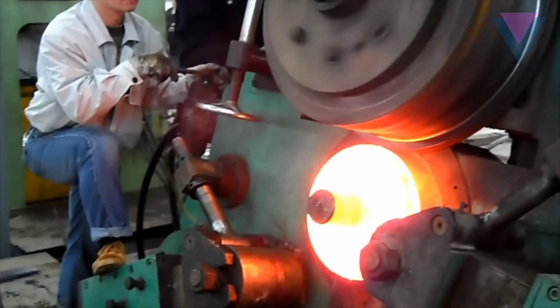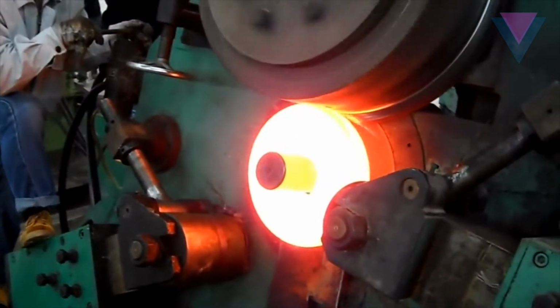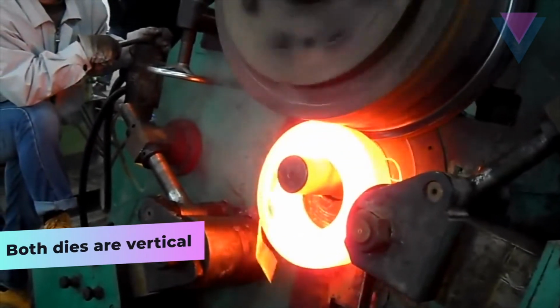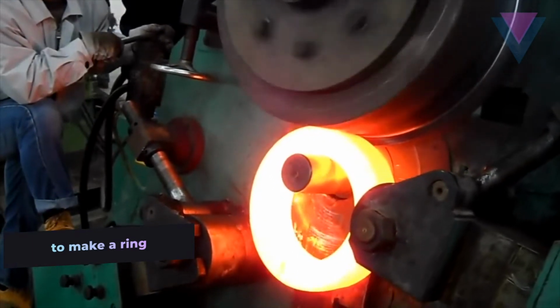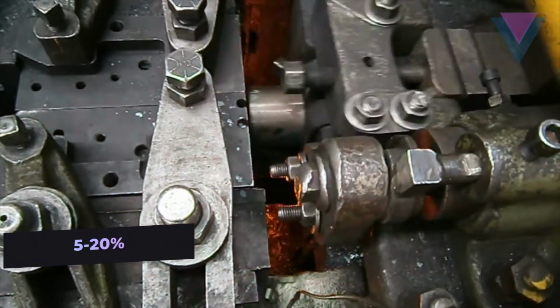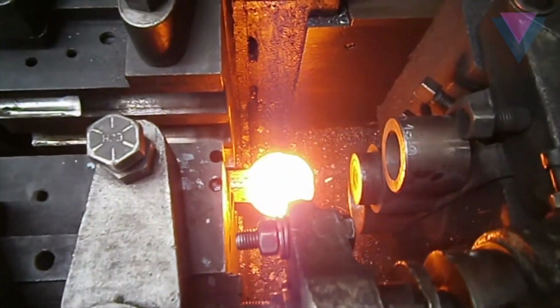The bottom of the machine can accommodate the pre-rolled rings placed there. The top die is inclined at an angle against the vertical axis, allowing the top die to rotate. While construction is on, both dies are vertically placed, allowing the ring to get rolled in the impression. Compared with a conventional closed die forging process, the rolling force amounts to just 5 to 20% in this production process. The rolling speeds up the production process of large-scale seamless rings.